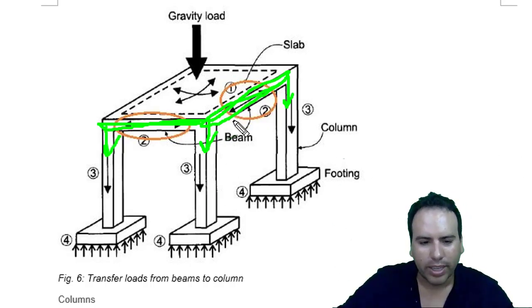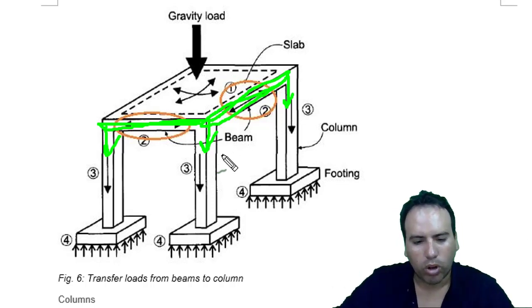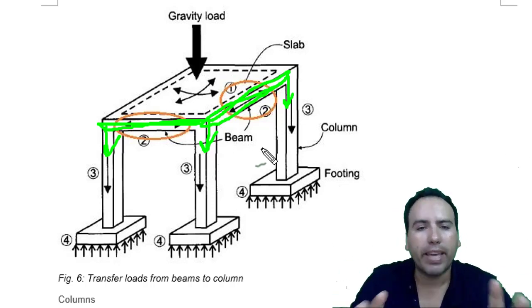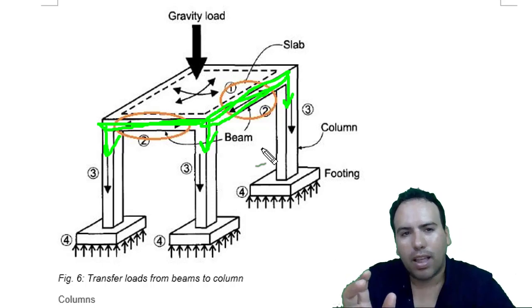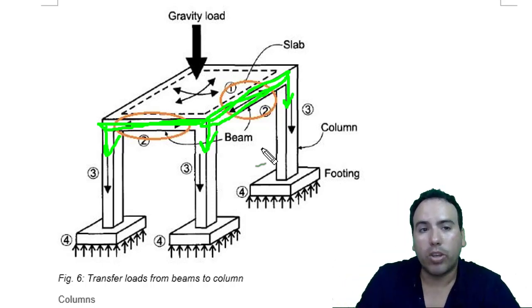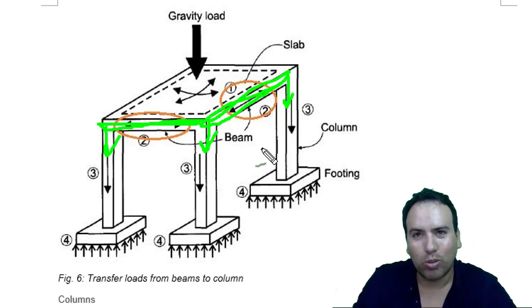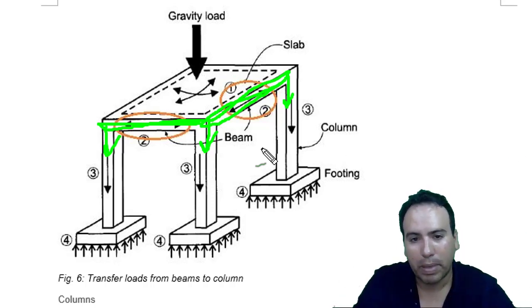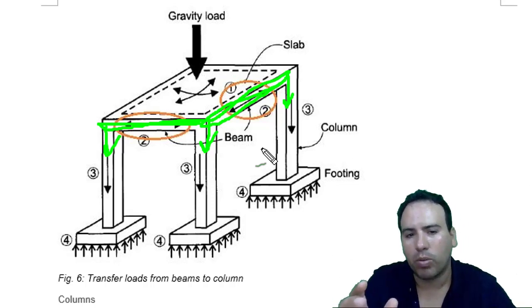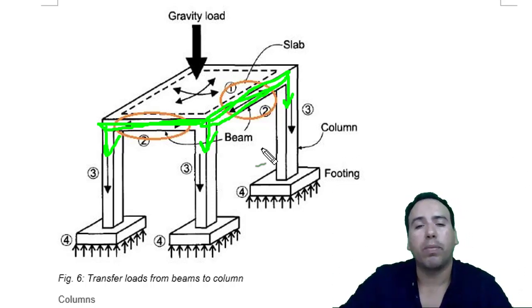If it's a wall, then it'll work all along the way, but you have to make a difference between what we call in Mexico a castillo, which is a tie column, and bonding beams, which are different. Bonding beams and tie columns work on walls, while the regular beam and regular columns work as a single element. It's very important.